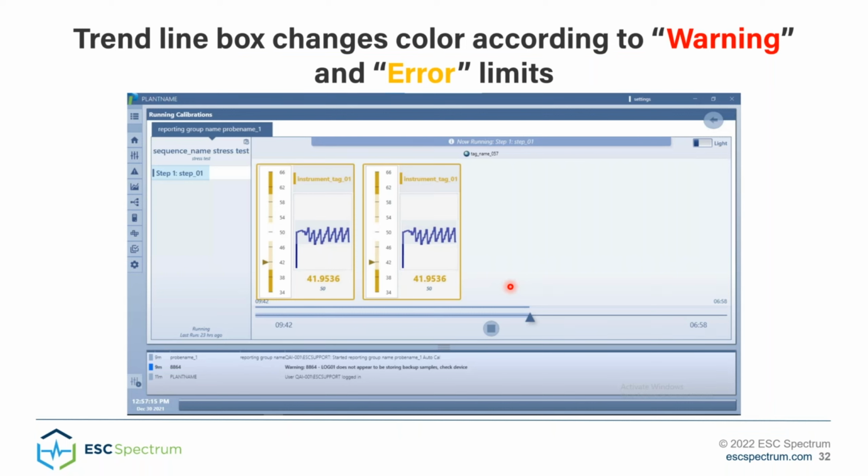The instrument indicators are designed to give you all the detail you need to know about your limits for that particular instrument. This is a test system, so it doesn't make a whole lot of sense, but this will be an instrument name here. You can see by the graph where your values are. This one is into the warning, which is the alternate spec area based off the current value. So the whole thing has turned yellow. The measurement values have turned yellow as well, and the expected values are down below that. And you can see the trend line here will go up and down with the instrument values.